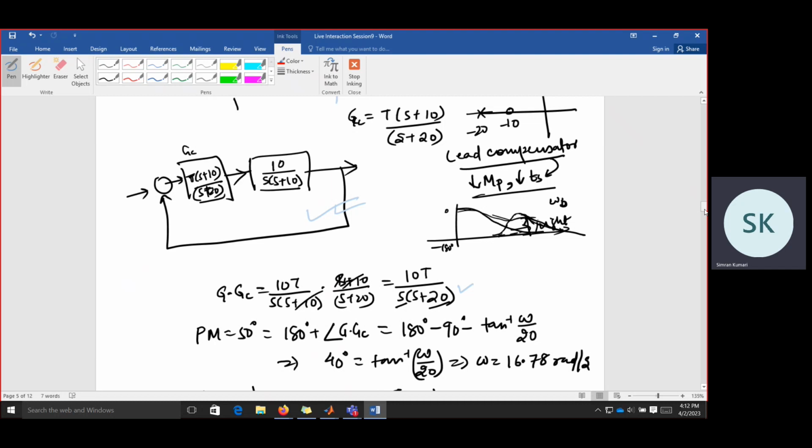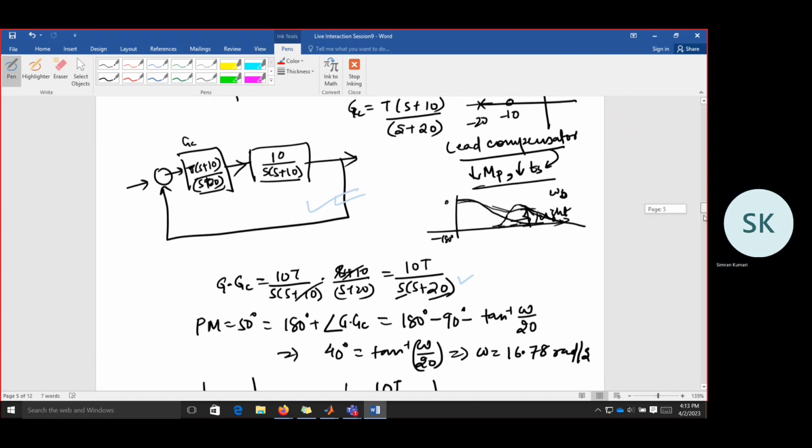Then we modify the root locus such that we have dominant poles, so we approximate the overall system with a second order system. For frequency domain analysis also, we approximate the overall system with a second order system. Since we have dominant poles, the overall system behaves approximately like a second order system, which has specific complex conjugate poles. So this is the overall idea.